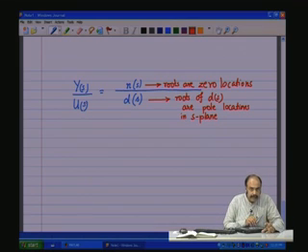It basically takes the time domain variables into the pole zero domain variable or the Laplace domain variable, which is a function of s, and that results in a numerator polynomial and a denominator polynomial, the roots of which form the zeros and the poles. The roots of the numerator polynomial are the zero locations in the S plane or the pole zero plane, and the roots of the denominator polynomial form the locations of the poles of the circuit.